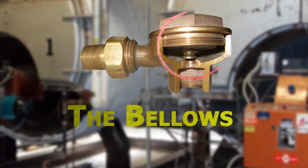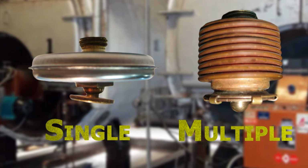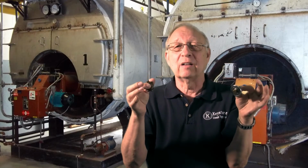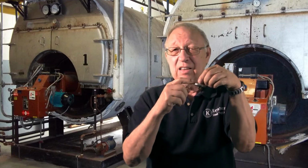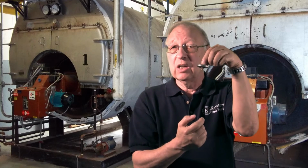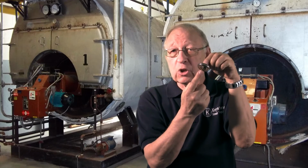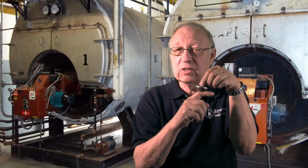At the heart of any thermostatic steam trap is the bellows. Once again, the bellows can be made from any one of several different materials and in either single or multiple convolution varieties. Inside of each bellows is a volatile liquid that reacts to its surroundings. Remember the traffic light? Well, when the bellows is surrounded by steam, the liquid inside of the bellows turns into steam, causing the bellows to expand. When the bellows expands, it causes the plug, which is attached to the bottom of the bellows, to close the opening in the trap seat, and thus stopping the flow of steam into the return piping system.